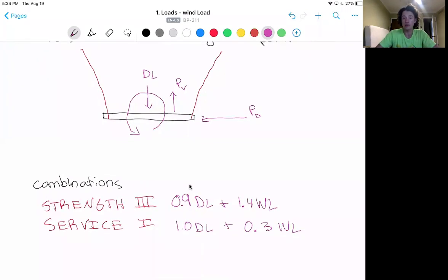The last thing I want to discuss with the LRFD method, which is really just for learning purposes here, is the future. It is what some more of the complex calculations we'll use, because the LRFD method allows for higher loads but more reductions, depending on the use, versus the ASD, or allowable stress design, which can be more stagnant: you have one reduction, and if your stresses are higher than what's allowed, then it's not going to pass, whereas the LRFD, depending on the situation, can allow for a more efficient design. But that was a digression.